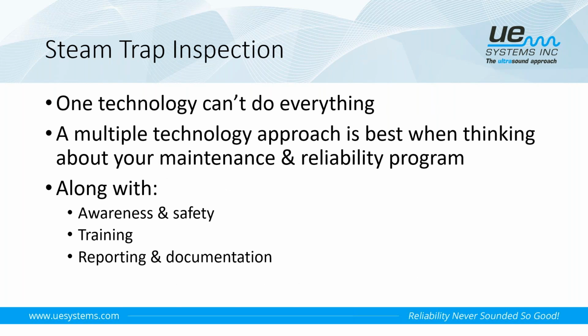Now, at UE Systems, we always promote a multi-technology approach. So in our case today, with steam traps, we're talking about making use of ultrasound and temperature, not necessarily an infrared camera. Certainly, if you have one, that's great, but just a simple spot radiometer to take inlet and outlet temperatures on these steam traps.